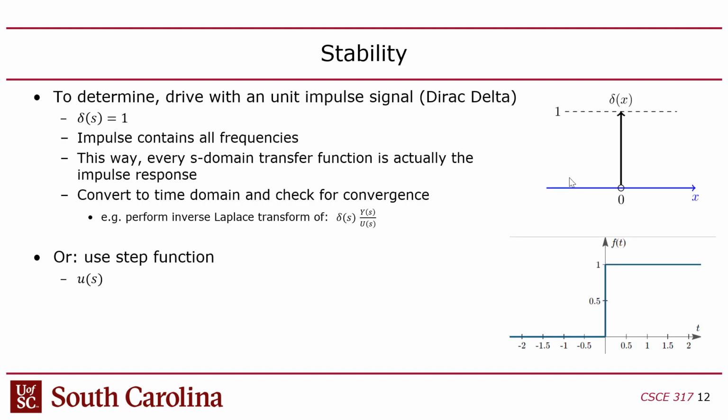Okay, so here's an example. This is the impulse function. This is also called the Dirac delta. So it's basically at time 0 you pulse it, and every other time it's 0. And then the step function looks like this. We have 0, 0, 0, 0, 0. At time 0 it goes to 1. And then it stays at 1, right? You don't have to necessarily return back to 0. It's just a pulse from 0 to 1. You guys with me?